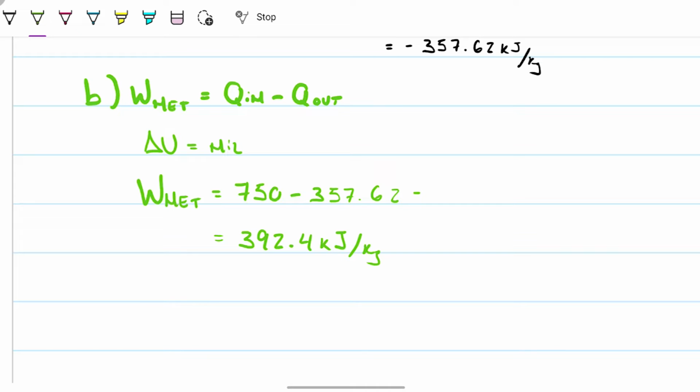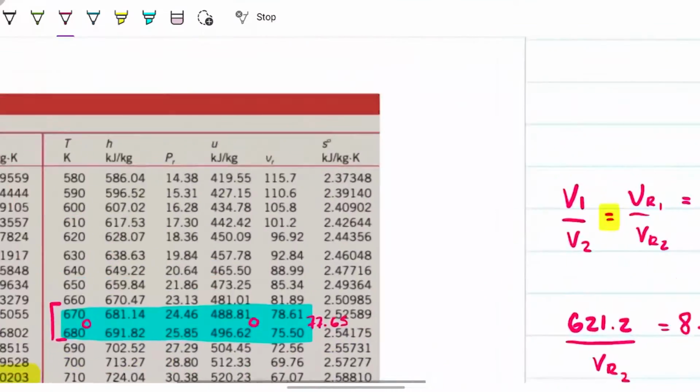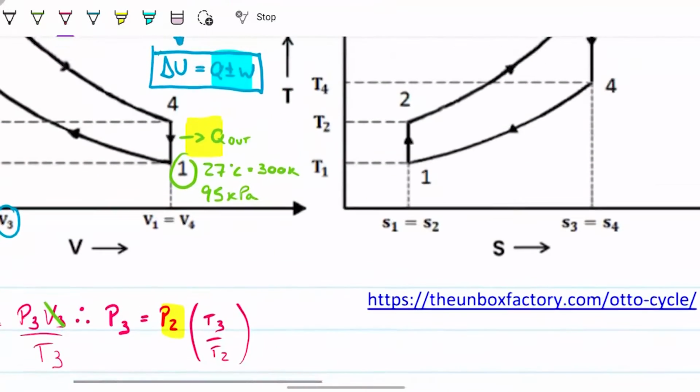And next up is part B, right? Now, I wonder whether we have enough information to be able to multiply this by the mass flow and then have the answer in watts instead of energy per mass. We need to check that. We need one state fully defined to be able to do that with all the info.